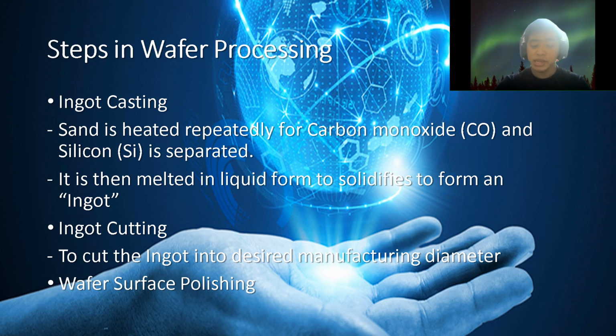The diameter of the ingot slice determines the size of the wafer. Larger and thinner wafers can be divided into more units, which helps reduce production cost. After cutting the silicon ingot, it is necessary to add a flat area or indent mark on the slice so that it is convenient to set the processing direction based on its standard in the subsequent steps.